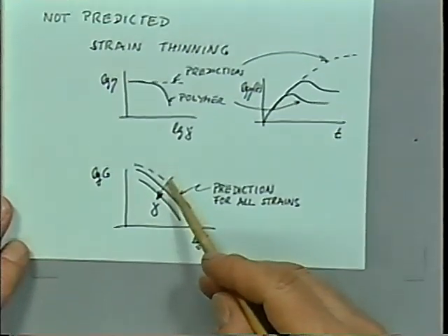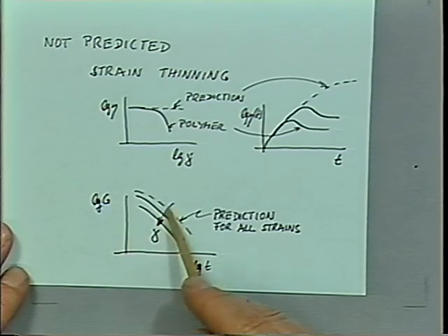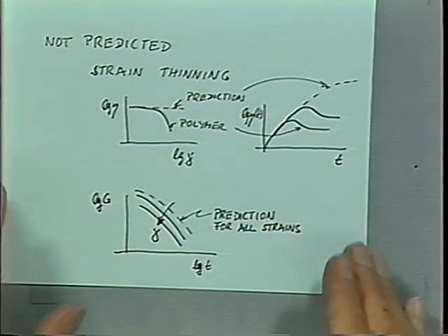And also we have to go back to Osaki's experiment of increasing strains in a step strain experiment, and explain why relaxation occurs faster at larger strains, but with the same distribution of relaxation times. The whole time spectrum is just shifted down, everything is shifted in an equal fashion. Next time we will expand on this concept. We will look at the large rubber-like liquid in a little further detail, and also go to large strain behavior, shear thinning behavior, and see how all this fits together.